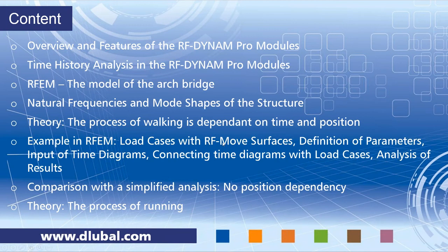We will define parameters. We will use parameters quite a lot today to make everything quite flexible, because it's quite an effort to do all the input today. You will see this in the example, and that's why it's really important to use the parameters to keep it flexible afterwards so that you can change things easily. We will input time diagrams, and we will use a quite new feature, the direct input of function terms, where you can use the parameters that you have defined. And we have to connect the time diagrams with load cases to define the position of the excitation cases. And of course, we will analyze the results and study this.